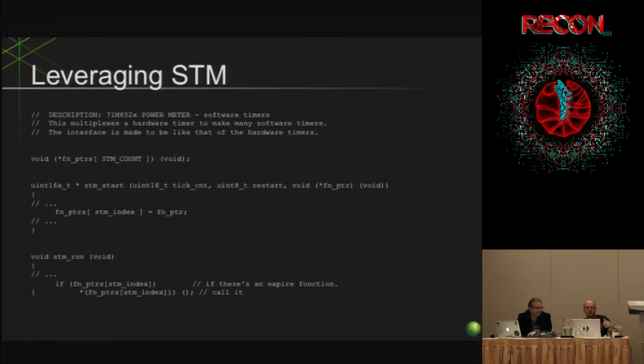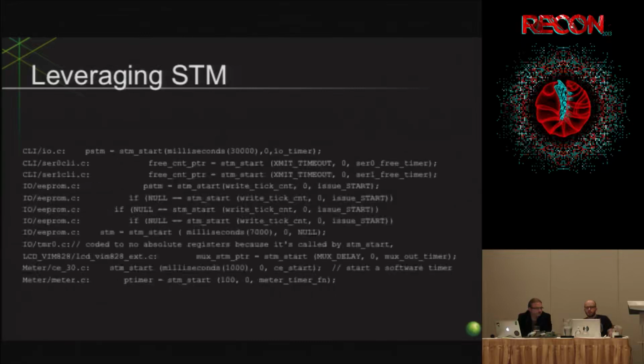And then it adds it to an array. Down below, after the hardware timer interrupt has flowed through, it'll hit this point eventually where it converts that function pointer out and calls it. It's called by a lot of places. The other thing that can be nice is that, let's say you can't directly call a piece of code because it's in a different bank, right? That can happen here and does happen in some cases here.